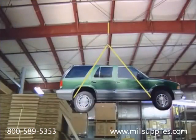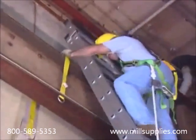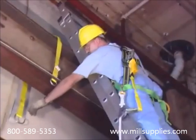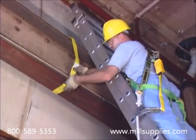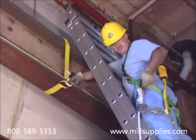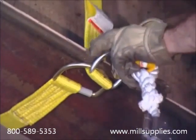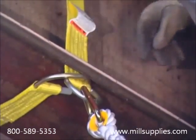When selecting an anchor point, remember, it must be capable of supporting 5,000 pounds per worker and be compatible with your anchorage connector. Attach in a manner which will limit the free fall to the shortest possible distance, never more than 6 feet when using a lanyard, unless you are using equipment designed expressly for free falls over 6 feet. Attach in a way that avoids a dangerous swing fall. Use your anchorage connector to attach to the anchor point and attach your connecting device to the anchorage connector.